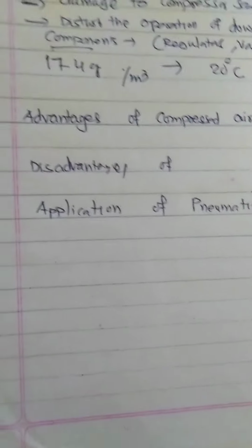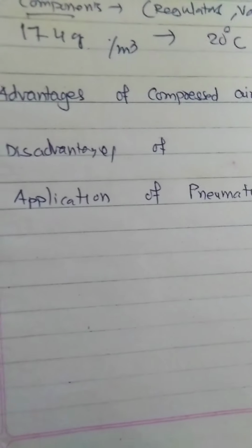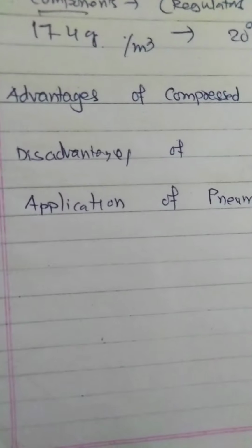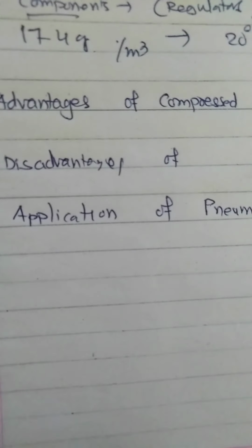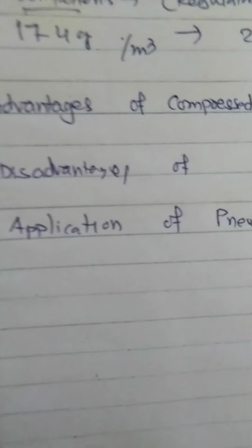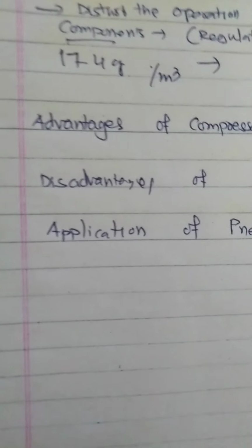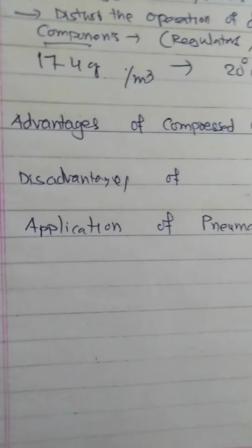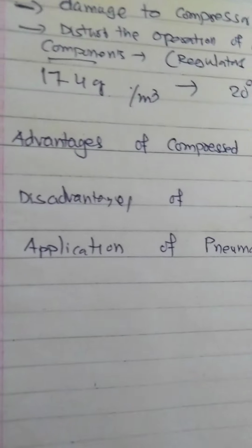Air equipment presents no sparks in an explosive atmosphere, therefore it can be utilized in oil refineries, chemical plants and other plants that have the problem of explosive atmosphere. Air equipment can be employed under wet and humid conditions because there is no electric shock hazard. The ever increasing number of pneumatic applications is due to research investments by the component manufacturers and the efforts of creative people who design and develop flexible and efficient pneumatic control systems.